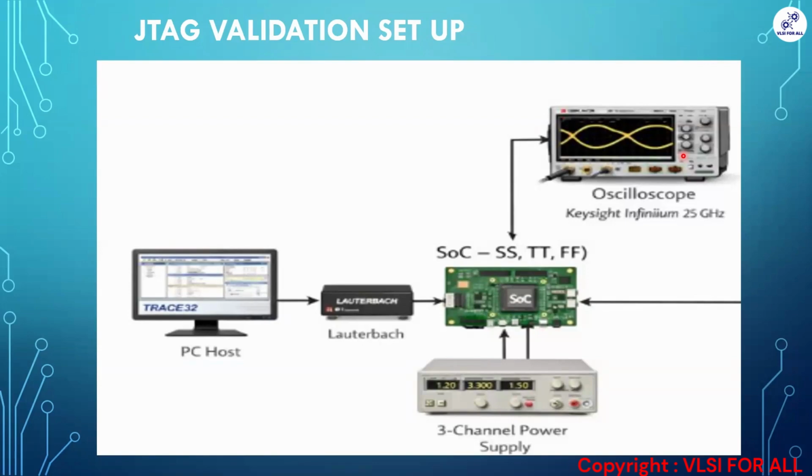Basically, you can tell in interviews that you can set up an eye diagram using the bit rate measurement and clock recovery. Using bit measurement and clock recovery, we can set up an eye diagram in an oscilloscope.